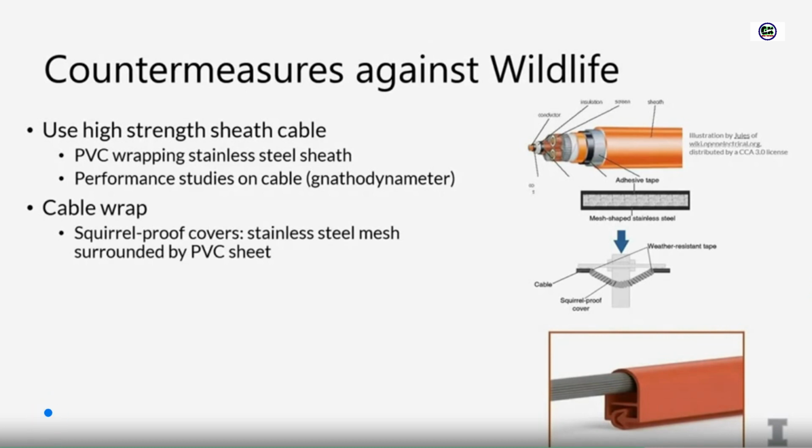Another thing you can do is buy cable wrap. So if you have a set of cables deployed, you can wrap them. There's certain tapes you can deploy on the outside. There's certain PVC sheets you can use, or stainless steel meshes and so on. You can put squirrel-proof covers on your devices, and so on.